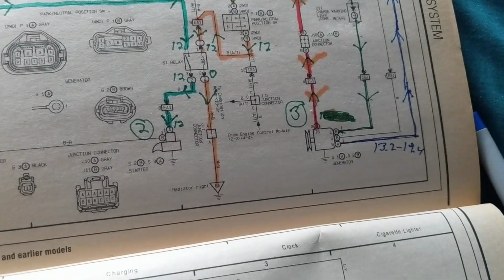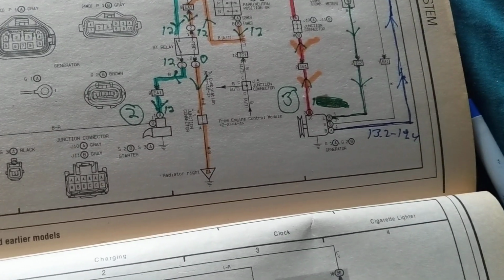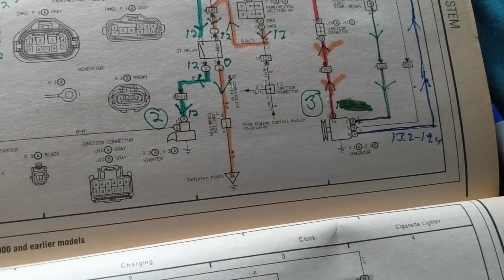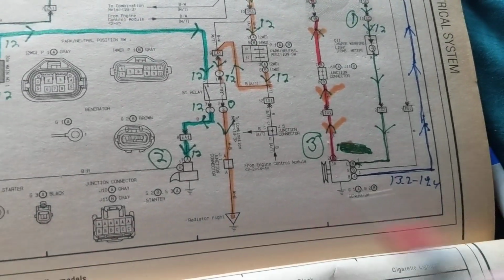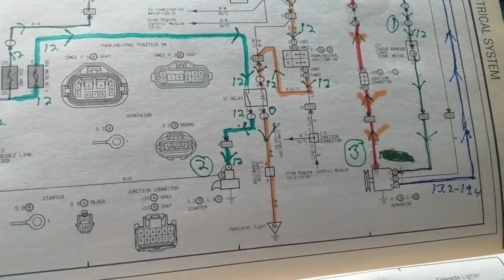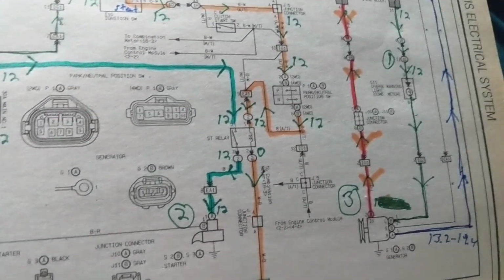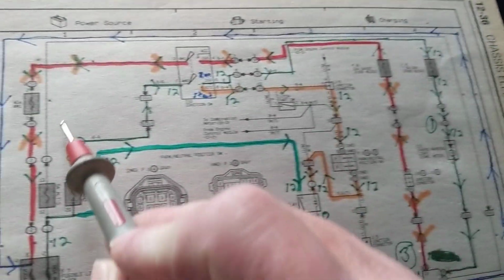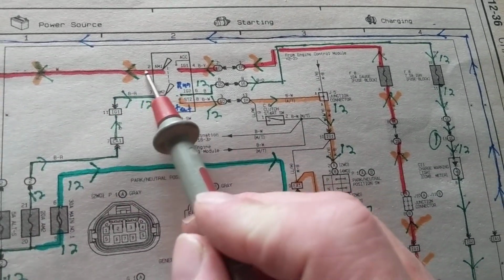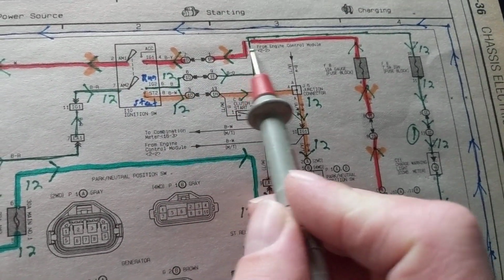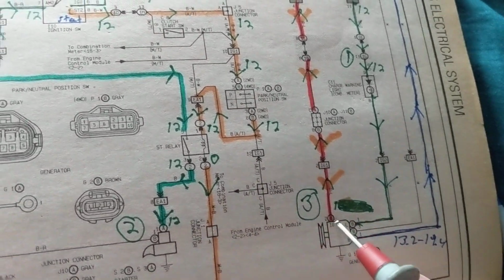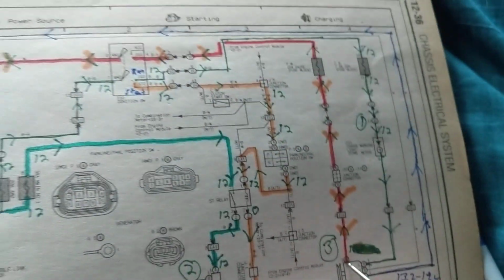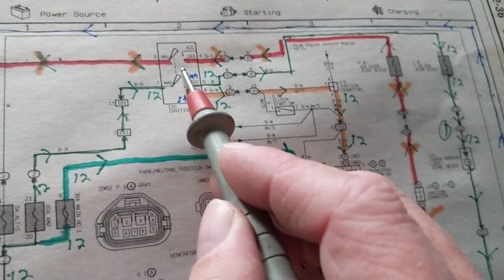the alternator to give it B plus, because after all, there is a regulator over there, transistors and diode, and they need B plus. They need 12 volts DC to start off. Once the alternator works, it gives back the DC that was rectified in that position. So, first thing is first. We follow this thick orange line, a red line. Going through this, we're giving the regulator 12 volts. That's number 1, this one, AM1.